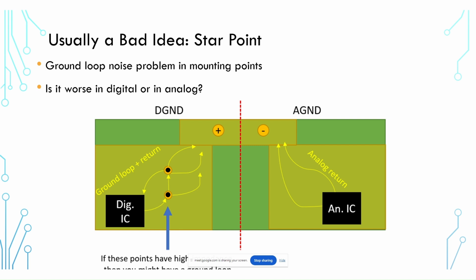So for example, when it has an AC input and you're bringing in the earth connection into the PCB. But in many cases, when you have these situations where you have multiple stitching vias connecting between grounds in order to provide consistent potential everywhere in your PCB, the most common objection I see to that, usually from beginners, is that, well, you're creating a ground loop. The ground loop that you're creating is probably so inconsequential that you'll never be able to measure it. So I would say focus on providing clear ground first, and then worry about the ground loops later.